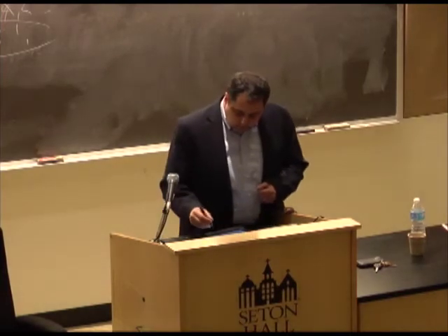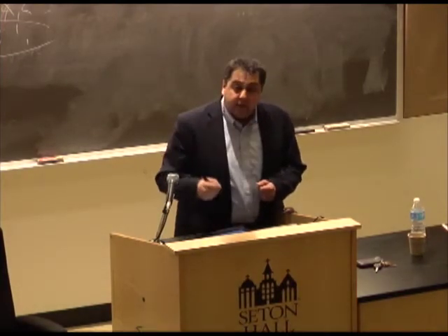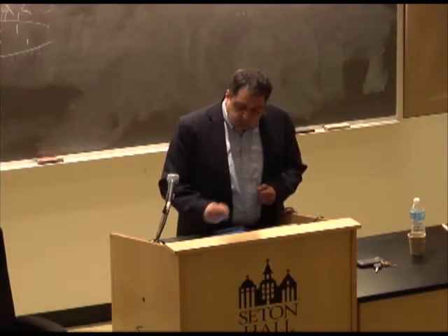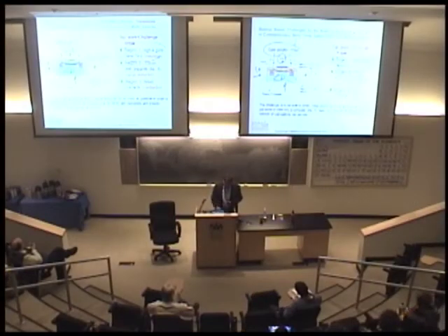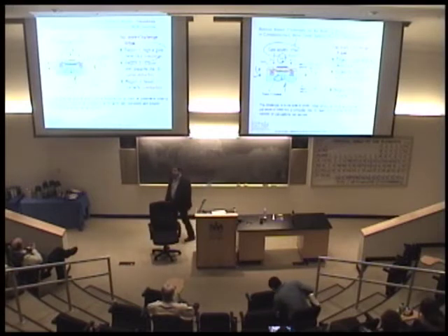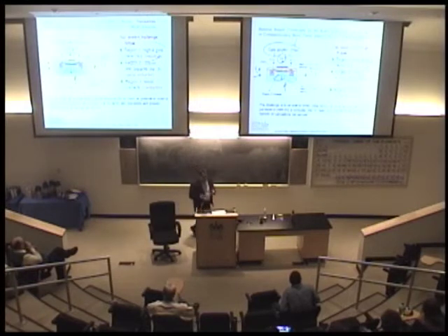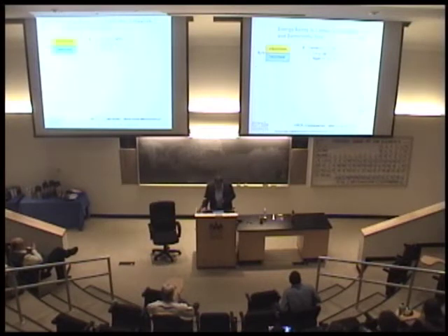So there are three regions that I'm going to discuss today. The insulator region, which is the yellow, the semiconductor region, and then the p regions, silicon-based mostly. And the third one is the conductor region, which the industry is now using copper for. It used to be aluminum, then copper, but next generation will be nickel-based. I will talk about why the differences.